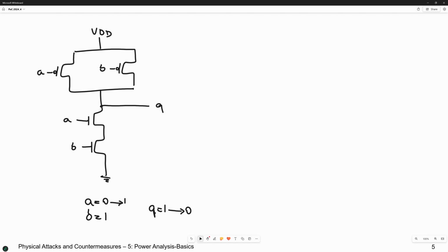these switches through the transistors, A and B, these PMOS and NMOS transistors, are not ideal switches. As we said, they have some leakage current, but they also are not super fast. They are not atomic. It means that in one, let's say, femtosecond or picosecond, they do not change their state. It takes some time.